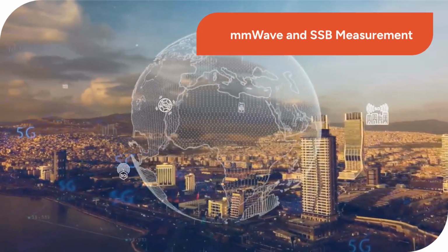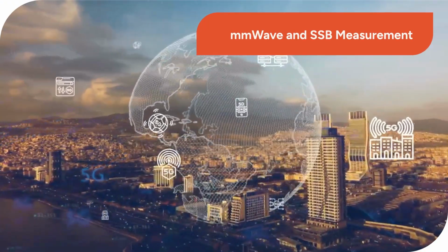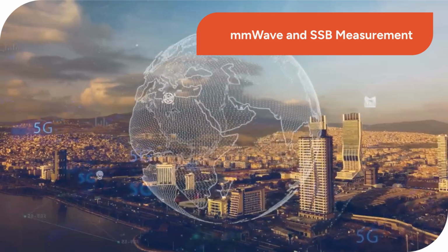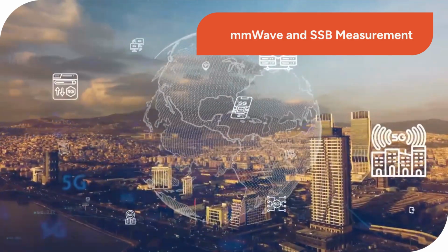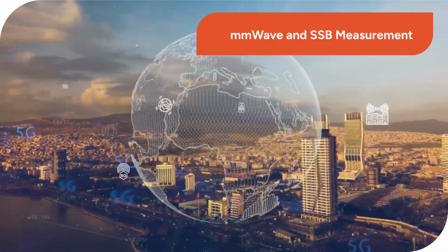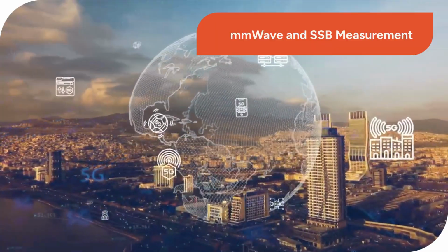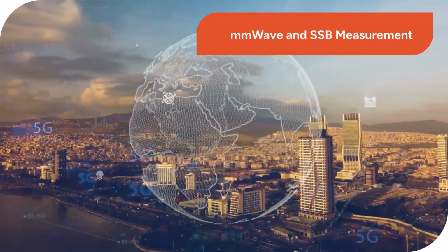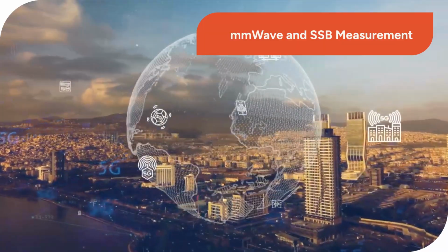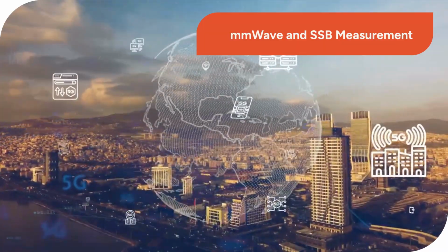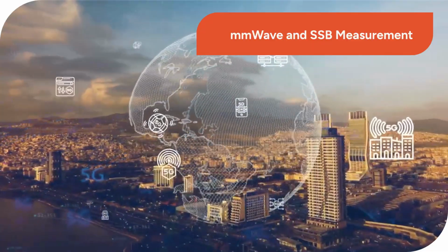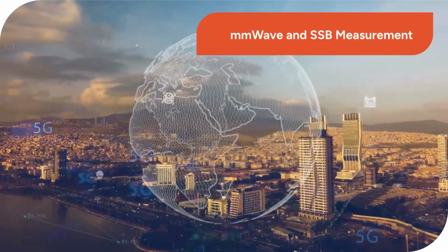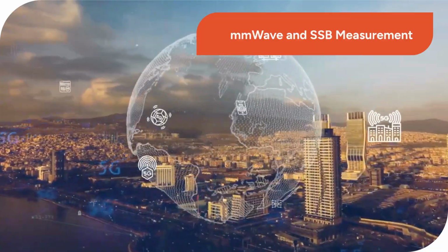In millimeter wave, coverage relies on narrow, focused beams. Before the UE can attempt RACH, it must first measure the received power of the synchronization signal blocks, or SSBs, transmitted by the gNodeB. The UE selects the strongest SSB. This chosen SSB directly informs the UE which PRACH occasion to use, essentially telling the gNodeB exactly which beam its preamble is coming from.